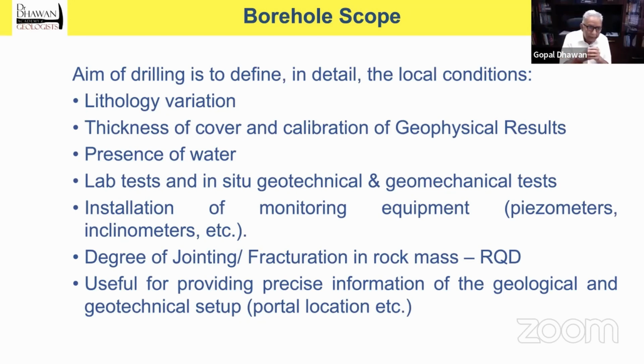And the main objective of drilling is to notice lithological variations, thickness of overburden, calibration of geophysical results, presence of water, that is water table, and collection of samples for lab testing. Then these can be used for in situ testing also. Holes can later be used for monitoring with inclinometers, piezometers, etc.